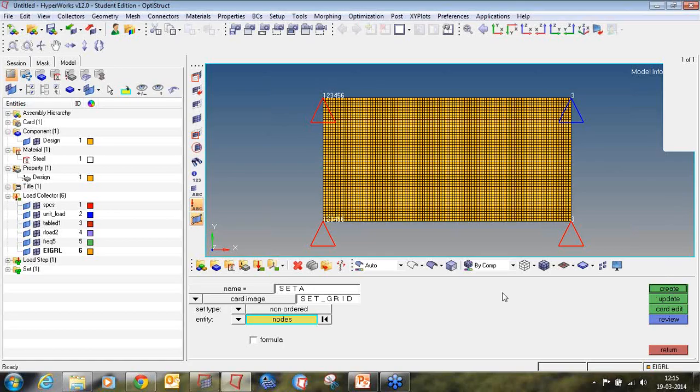With FRF simulation, the amount of data generated can easily create a big result file. It is a good practice to work with a set where the user can specify only the points of interest. This will reduce CPU time and the amount of data to be saved. So we will create a set of outputs and include damping for the frequency response analysis.